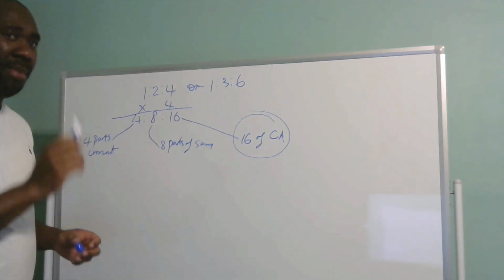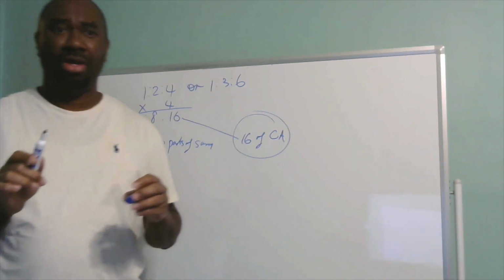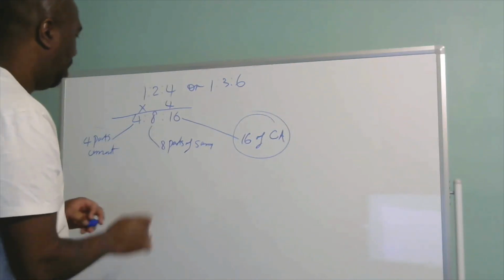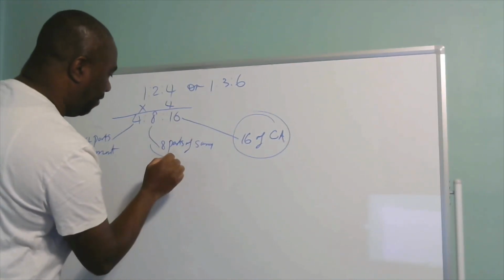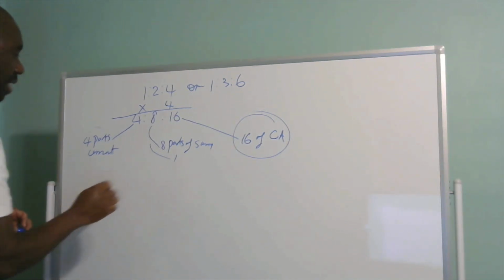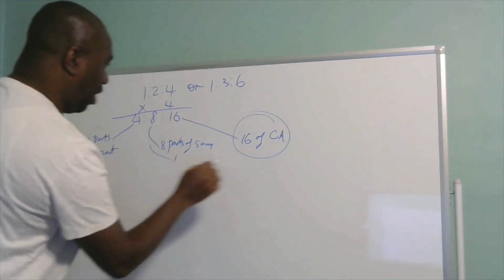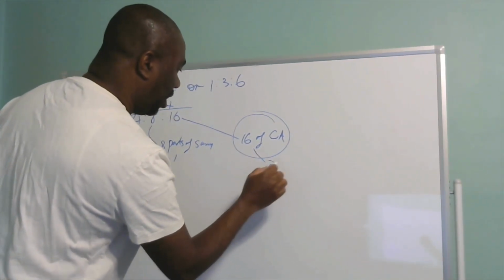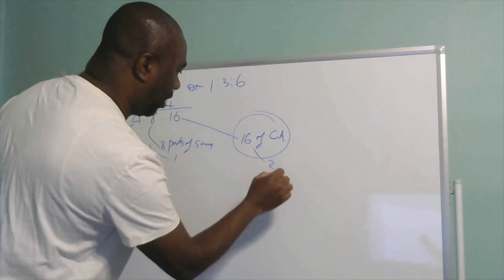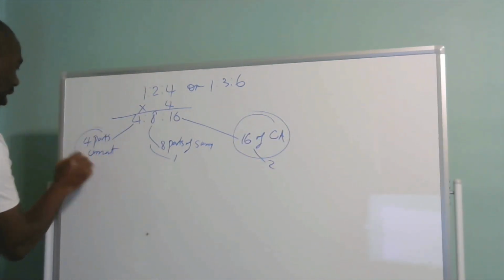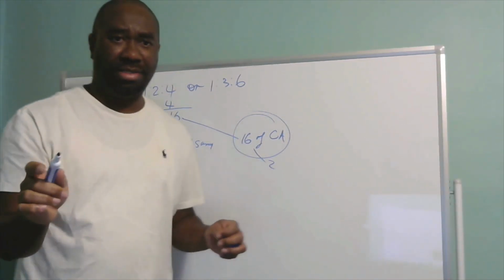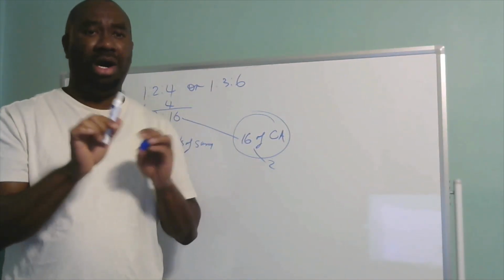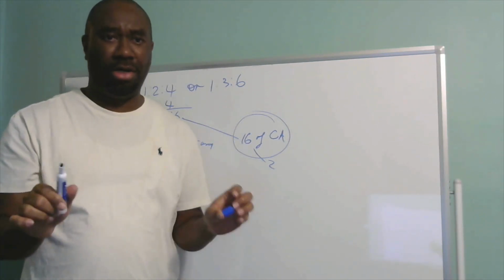But a regular practice that I've seen on site is that they run on the 8 barrels of sand first, right? And then they run on the 16 barrels of coarse aggregate secondly, and then they run on the 4 parts of cement on top of that aggregate. That is not the way concrete mix is supposed to be done, right?